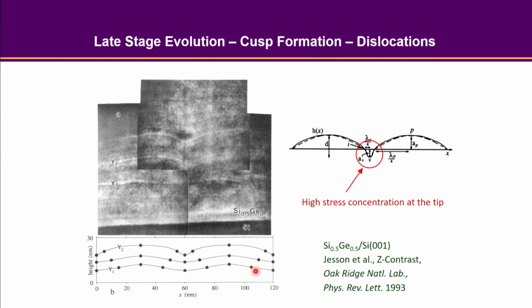But as time progresses and the amplitude is amplified, you are going to see an asymmetric profile between the peak and the trough. You are going to see a much wider and broader peak, but the trough is going to be very, very localized. The curvature is bigger, and in the end, there could be some defects nucleated at the trough, all right?